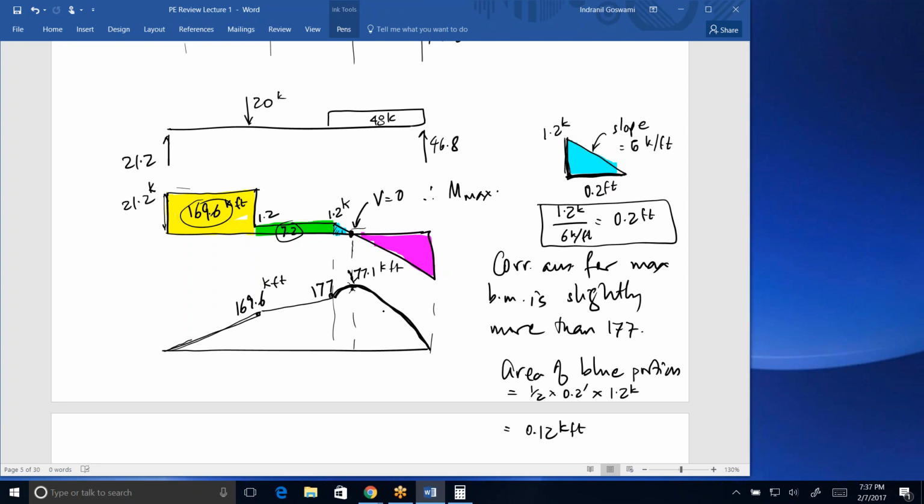So in this particular case, you had to work up at least up to this shear diagram to be able to answer what your maximum bending moment is, because until you get to the shear diagram fully, you don't know what the zero crossing point is for the shear, and therefore you don't know up to which point to calculate the areas.